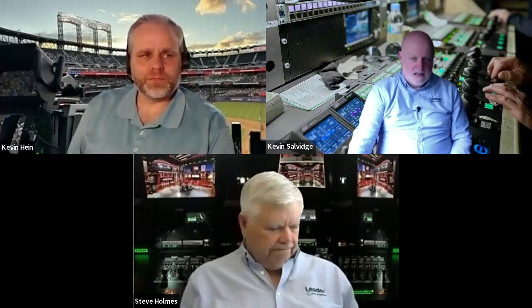Outstanding. Thank you for that introduction. So let's get started. As video consumption increases and content providers move towards higher quality content, bandwidth capacities become even more important. Broadcasters transitioning from serial digital interface, or SDI as you and I know it, infrastructure to IP technologies for uncompressed video transport within the broadcast facility have been using SMPTE 2110 and 2022-6. The IP environment offers bandwidth savings, decreased operational costs, and a common data center model for operation. However, a single-step transition approach from SDI to IP is not feasible for most broadcasters. So that means that SDI and IP are going to coexist for some time into the future.